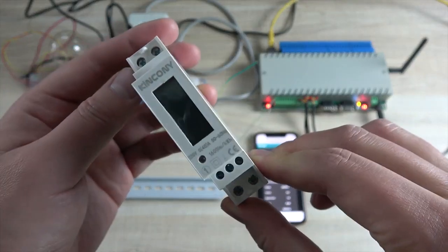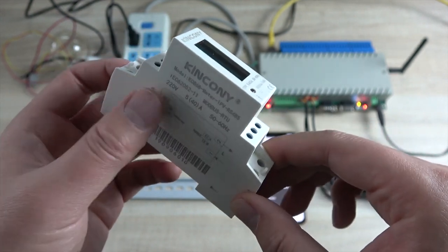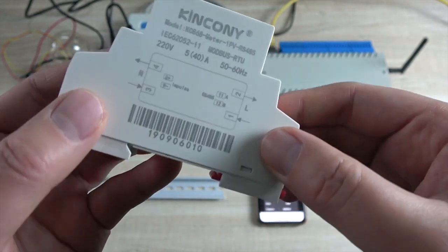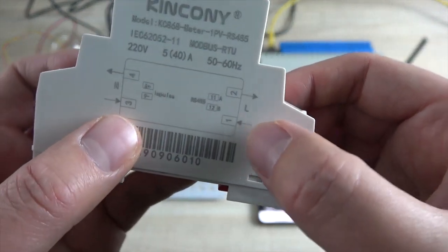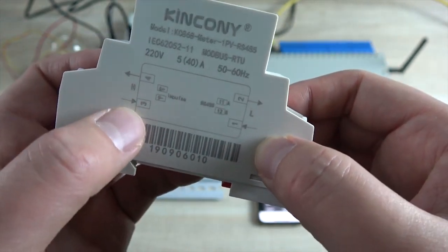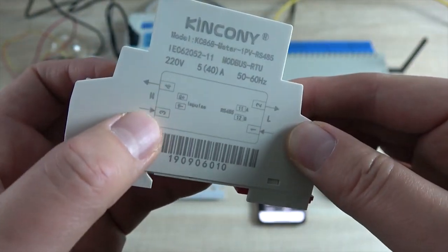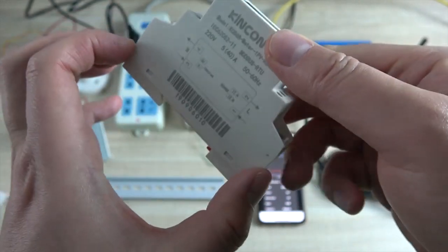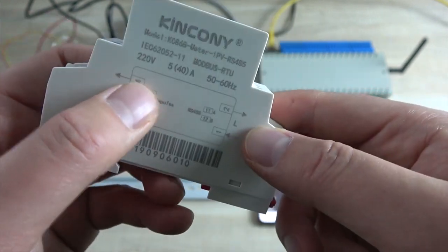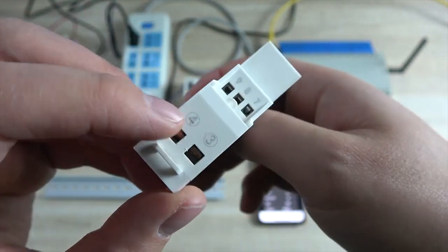This is our electrical energy meter. This is a single phase; we also have a 3 phase, but for this video, for example, we just use a single phase. You can see there are many screws, and they have the labels 1, 2, 3, 4. This is the live line, and this is the neutral line. This 1 and this 3 are the input for the live line and neutral line, and this is for the output, 2 and 4.